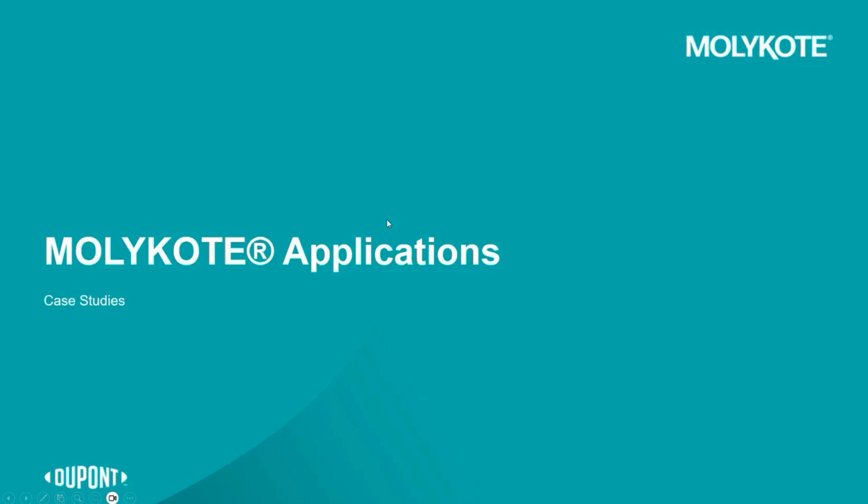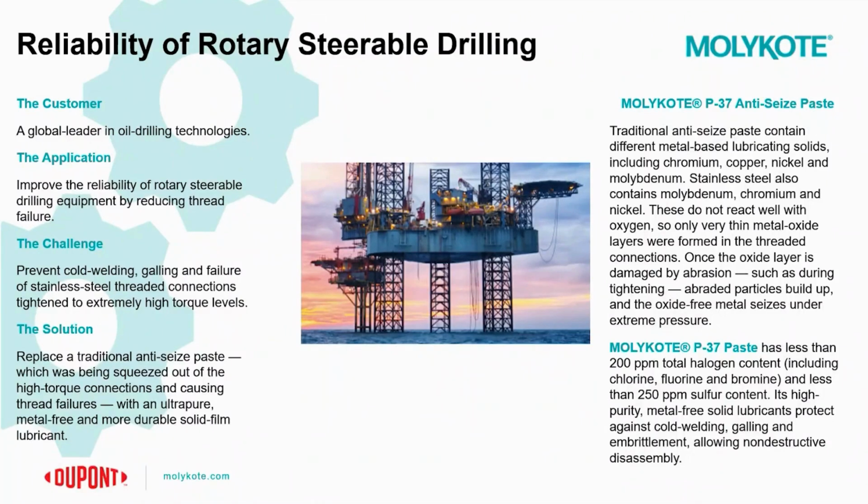So next we'll take a look at a specific application. In this particular application in the oil and gas market, we have a customer who's a global leader in oil drilling technologies, and the application is to improve the reliability of rotary steerable drilling equipment by reducing thread failure. The solution here would be some sort of anti-seize thread paste. The challenge in this application is to prevent cold welding, galling, and the failure of these stainless steel threaded connections, which are tightened to very high torque levels.